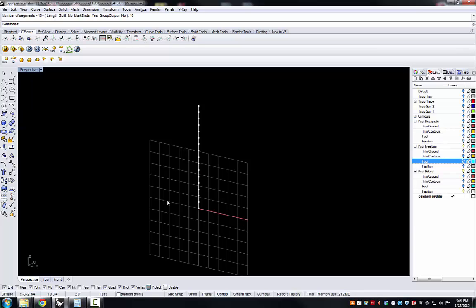And a very good rule of thumb is that if you add 2 risers and 1 tread, that should come to somewhere between 26 and 27 inches. So 2 risers at 6 3/4 equals 13.5 inches. That means to hit 26, we need at least 12.5 inch treads. We could make them 13 to round that up a little bit.